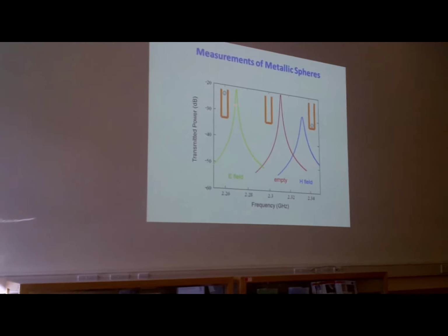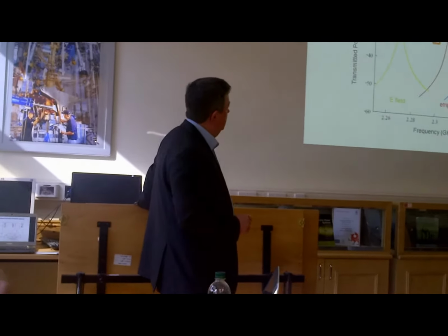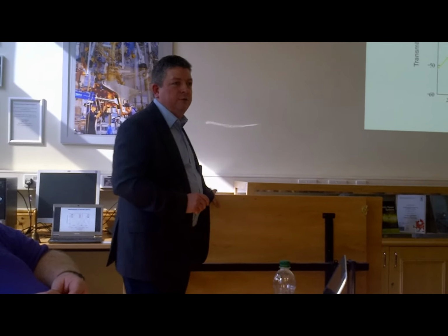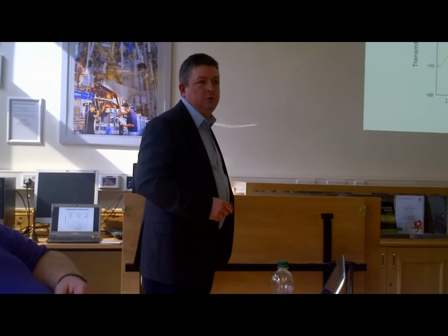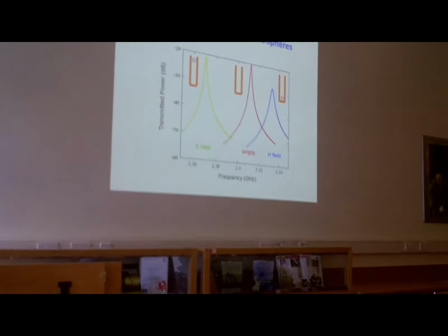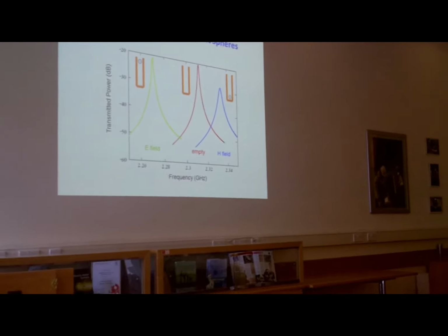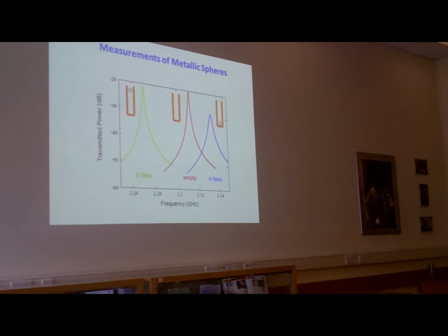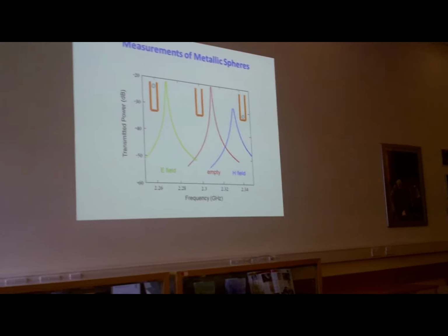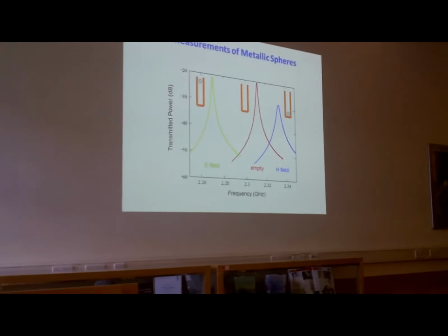And this is what you end up with. You get different types of behaviour here. This shows you what happens when you introduce, for example, a little metal ball into the electric field. This is the empty cavity response. So what you find is that when you put the ball into this electric field region, and it's metallic, you end up with a strong reduction in frequency, because nothing produces a larger electric dipole moment than a metal, because the internal field is reduced completely to zero, or almost to zero anyway.